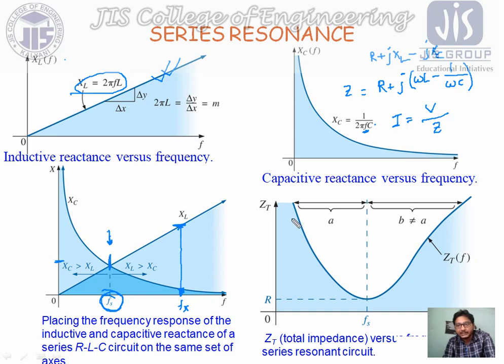And similarly, this is the overall impedance. As we know, whenever we change the frequency, our XL and XC change, but our resistance is fixed; there is no change in the resistance. In this particular resonance point, when XL is equal to XC, as we have already seen, our impedance Z will be only R. It means the inductor and capacitance effects nullify each other, so this overall part will be 0, and our Z will be only R. Previously our impedance was R plus something, now we get Z equal to R.